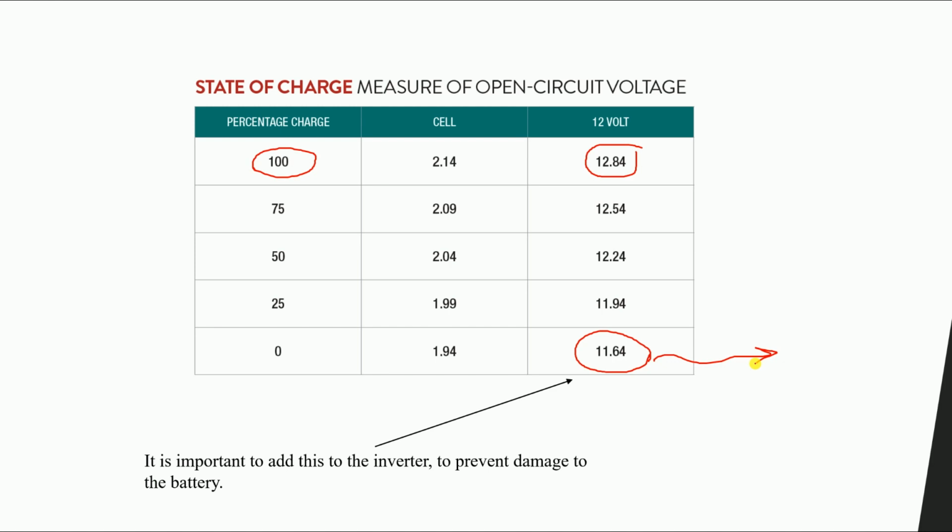My own suggestion is that if you are using lead acid batteries, for example, with 50% depth of discharge, and there is another source like the grid, then you can assume 50% state of charge or depth of discharge, which will be the same inside the inverter itself.